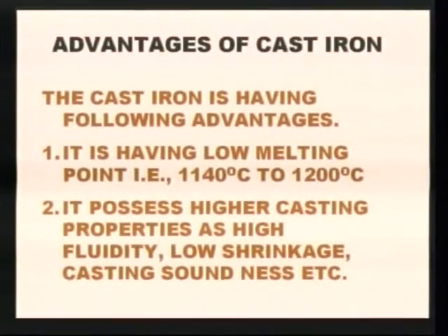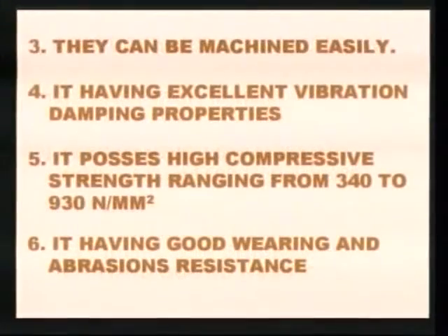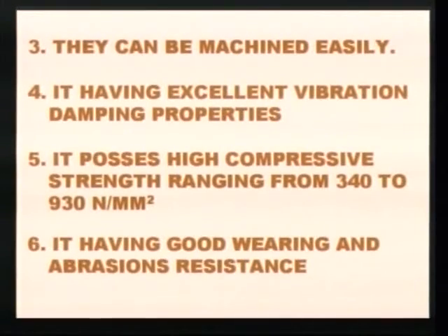Second, it possesses higher casting properties such as high fluidity, low shrinkage, casting soundness, etc. Third, it can be machined easily. And fourth, it has excellent vibration damping properties. Fifth, it possesses high compressive strength ranging from 340 to 930 Newton per mm square. Finally, the sixth advantage is that it has good wear and abrasion resistance.